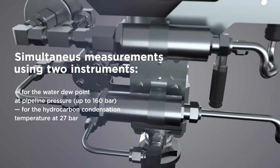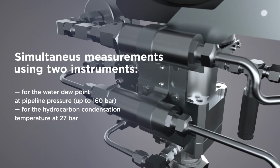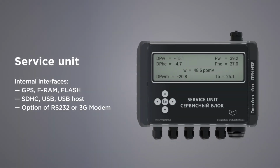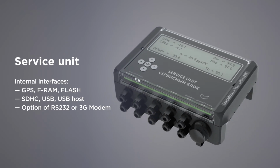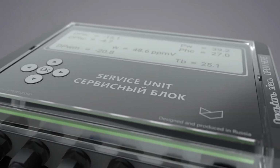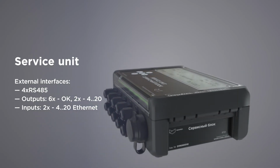If the gas is not purified, the combined system can be equipped with a filtration unit based on an inertia gravity filter. A service unit recalculates the water dew point measured at 27 bar to the operating pressure of the pipeline. The service unit can be used with Vympel analyzers as a secondary unit to provide not only conversion and recalculation of measured values, but also additional data interfaces and a display.